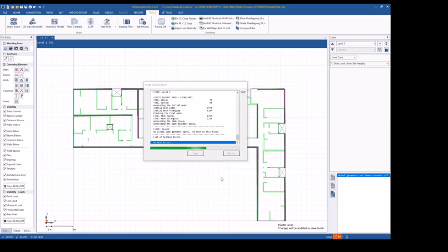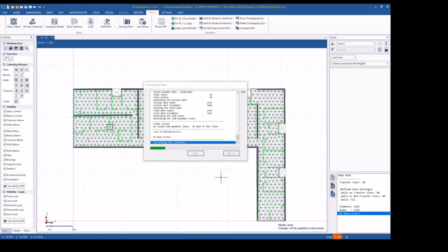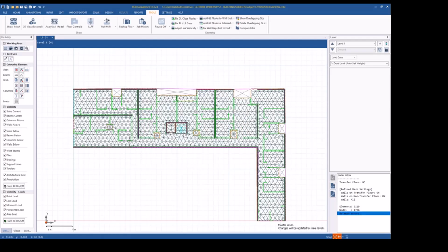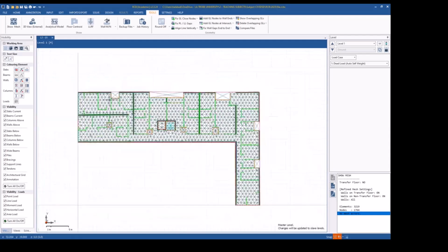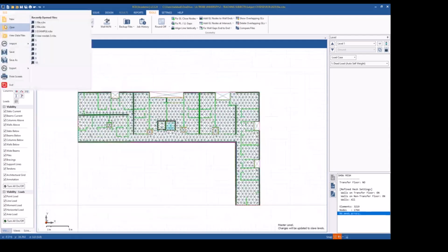That's why it didn't do anything, but let's read the message carefully. Basically what I did, I just chose a 0.75 mesh size, and I rounded the decimals by 50 mil. So all good here. I'll just hit exit, and now it's happy. No issues. I suggest you always save.